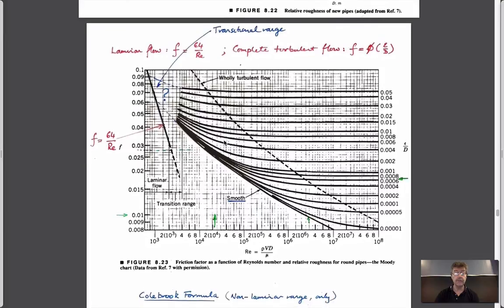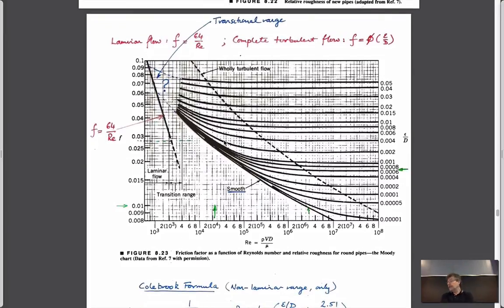This is exactly what we're going to be dealing with. And so really what we've done for ourselves is rationalize how we can come up with some chart that defines what the loss of energy is on our pipe system. In other words, what we have to overcome by putting extra energy into the system by pumping. And we've defined it as a function of Reynolds number. This is 1,000. This is 2,000 right here. This is the term that we talked about that we derived for simple laminar pipe flow.